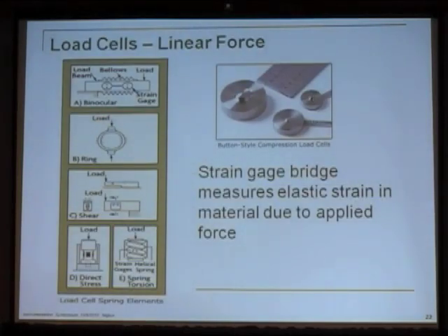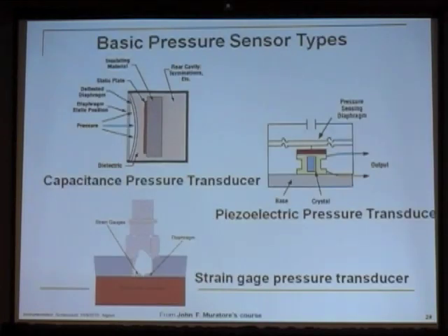Load cells are generally strain gauge based, at least the ones we use. So again, you're getting back to this idea of a strain gauge as a basic measurement unit. Pressure is also often a strain gauge. Most of the pressure measurements we do are strain gauges.